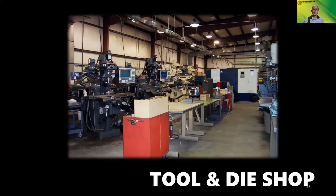Tool and dies normally are ready-to-use products, either as a standalone, such as molds, or as an attachment to a machine, such as a die. The products of the tool and die industry are typically made by mold and die makers using general, conventional, and specialized metal cutting technology like computer numerically controlled cutting machines, or CNC, employing special tool steel materials which are either pre-hardened or undergo heat treatment after the desired tool has been cut to shape.